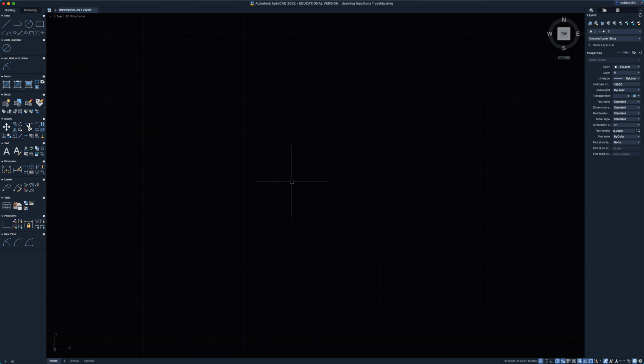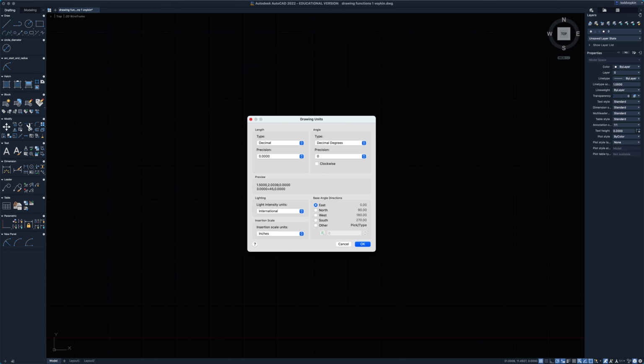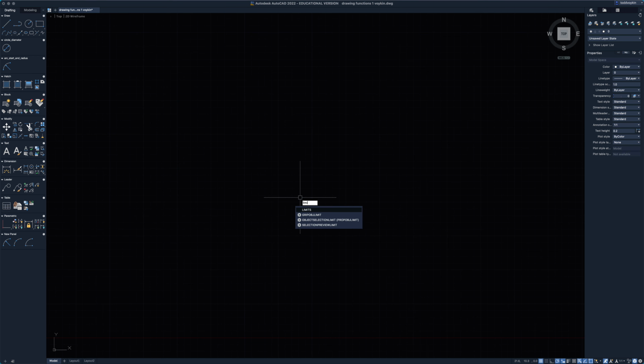And that's done. Now remember, whenever we open up a new AutoCAD.dwt drawing template, we need to change the units and set up the limits. Now, if you're using your drawing template that you've created, then that will be done for you, but in this case it's not. So we're going to start off with units, and 1 decimal place is good enough, and millimeters, okay. And the limits, we're going to set up to an A3 paper size with a 0,0 bottom left corner and a